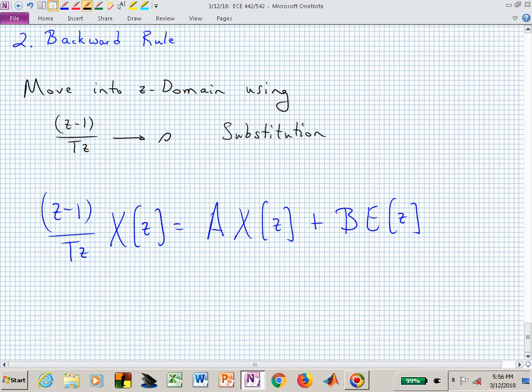Do you remember what we did in one of the first steps of this process before? We're now in the frequency domain for the discrete time setting. Let's clear that fraction on the left, multiplying both sides by capital T, z. Now it's a little more complicated because now we're multiplying not by just a constant T, but an operator, this complex frequency variable, z.